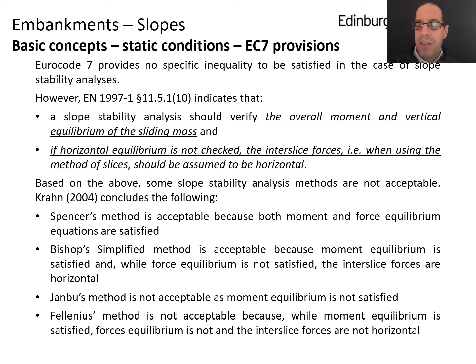Bishop's simplified method, that I also showed you last year, not unlike Spencer's method that I didn't mention, has different assumptions. Bishop's method is a method that you can use and is compliant with Eurocode. Because the assumption in that method is that the interslice forces are horizontal, but things like Janbu's method or Fellenius' method that is so popular cannot be used because moment equilibrium is not satisfied. And that brings some challenges.